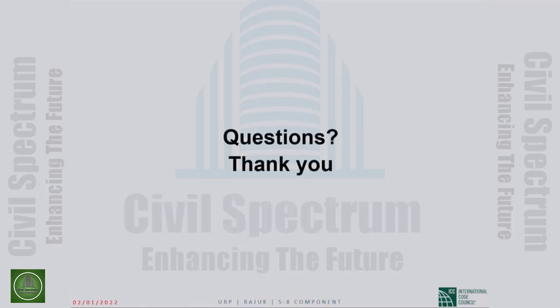But that is definitely in the future, not now. Wind design so far is elastic. Seismic design has not been elastic for probably 100 years now or more, pretty much from the beginning. So that's a very fundamental difference. That's probably the best answer that you will get to this question.